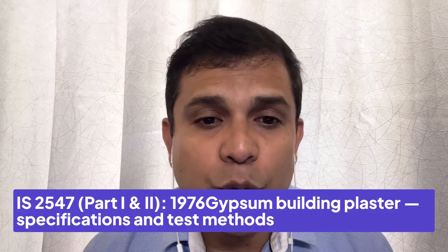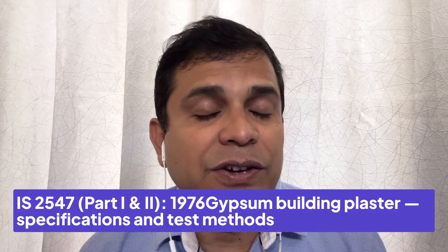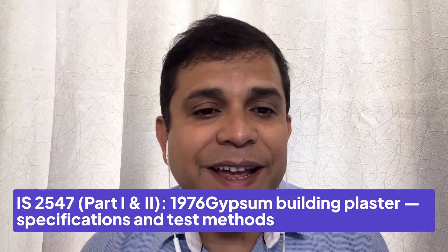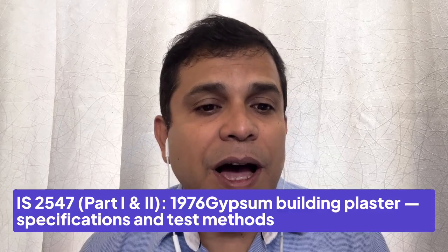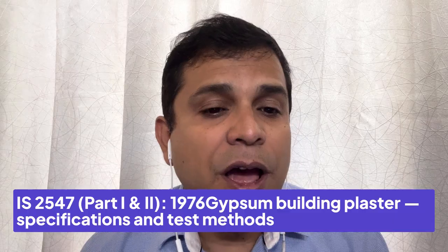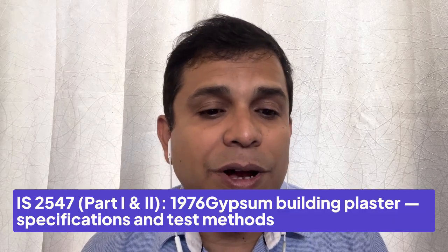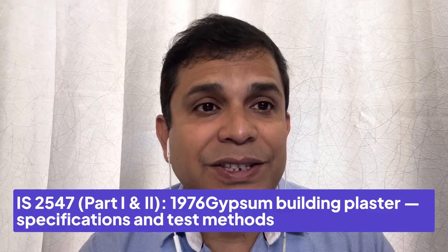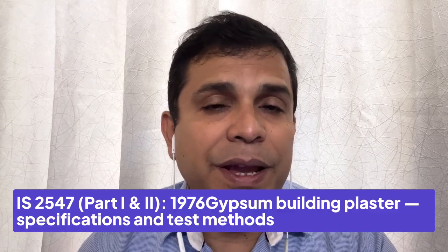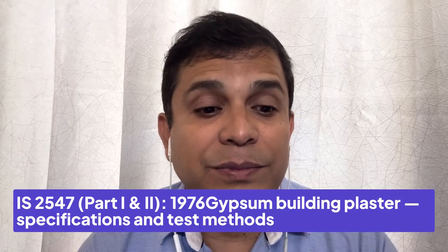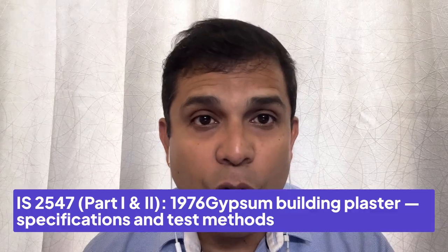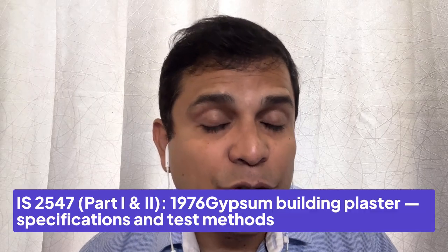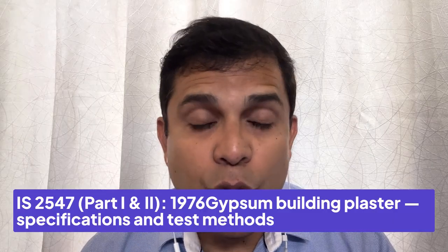Now, what is the relevant IS code? The relevant IS code is IS 2547 Part 1 and Part 2, the gypsum building plaster specification and test methods. IS 1288 is the method of test for mineral gypsum. IS 1727 is the test for pozzolanic material. IS 8272 is the guide for plastering and pointing on walls. These are all the codes we need to follow when dealing with gypsum plaster, because whenever the material arrives, you need to check whether the gypsum is adequate and as per the code or not.